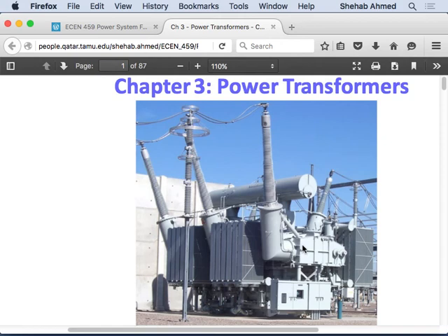For some reason, the winding is touching the chassis from inside, or there's a conductive path inside connecting the high voltage to the chassis, then the chassis itself will be a big electrocuting device, right? You touch it, you die, right? So that's why typically the chassis, for safety purposes, will be connected to ground, right? If you have a live conductor coming into something connected to ground, you have to make sure you insulate properly, right? Otherwise, you will have arcing and flashovers occurring, right?